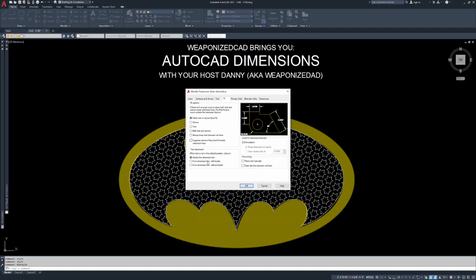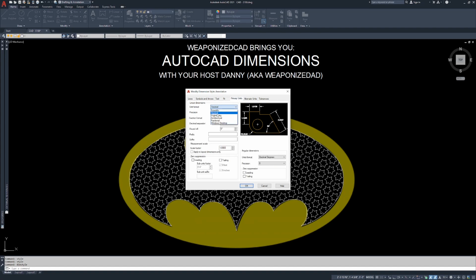The fit tab, we don't really need to touch anything here. The only thing we need to see is that annotative is checked here. Primary units, I'm going to change these to architectural with the precision of 1/16 of an inch. Fraction format, we want it as diagonal because it just looks nicer. You can keep it as horizontal or not stacked.